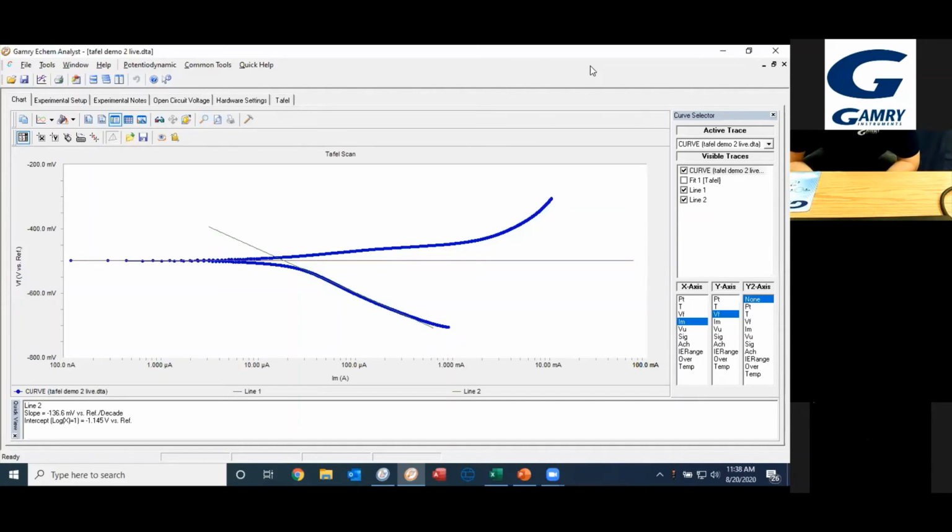I can't say for sure it's going to work all the way across the board. You'll just have to give it a shot to begin with. But one good thing, at least in the sense of corrosion inhibitors, is that you have bare metal, and you want to see how well your corrosion inhibitor performs. You run this experiment on the bare metal, and then you add your corrosion inhibitor and see if your corrosion rate goes down significantly. So yes, you certainly can. It's been done, and you can try it. There's no reason it shouldn't work. But in terms of, well, are you using the film for corrosion protection, or are you trying to get other information from the film?